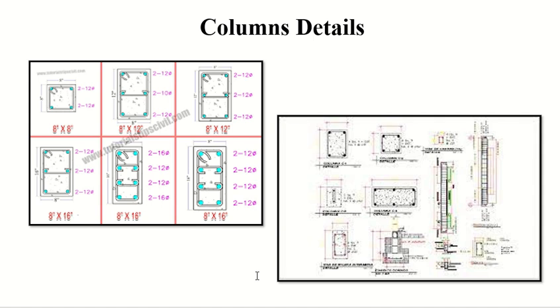What is this? Stirrup. How many stirrups? 1? 2? How do we know they are 1 or 2 or 3? From the size? From the hooks. How many hooks you have? Every stirrup will have a hook. Every set of stirrups will have a hook. So how many hooks you have? 1 here and here. If you see more hooks, that means that it could be more.